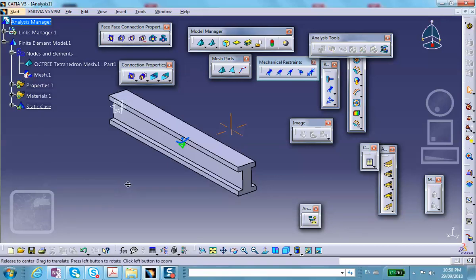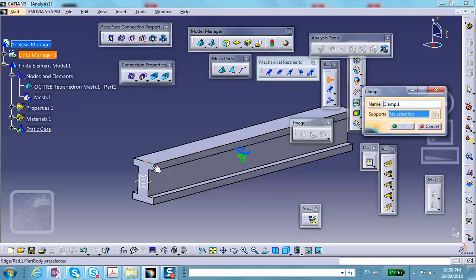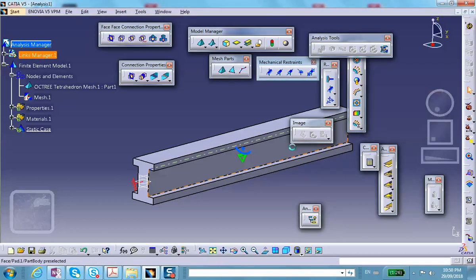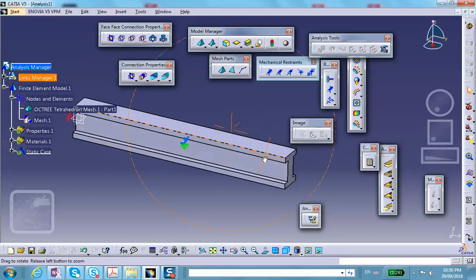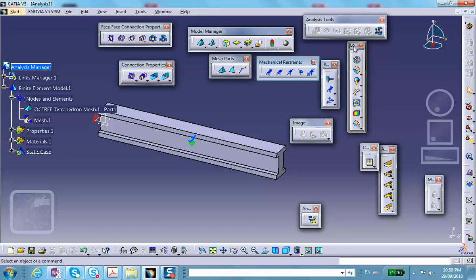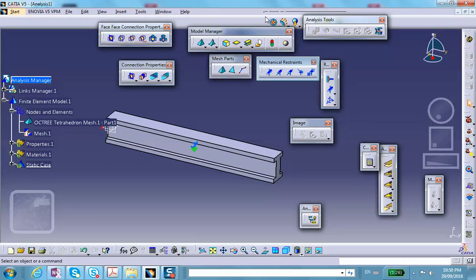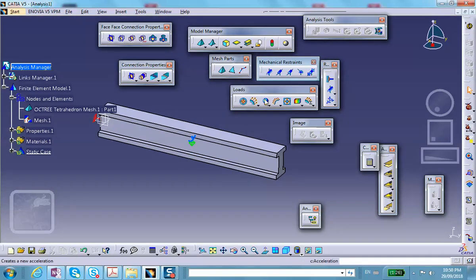All right, good. So this end is clamped. Where is the clamp? Right here. This face is clamped, and the load is coming from acceleration in the direction z, negative z. So where is that acceleration business? If you look at the loads toolbar, which is right here, where you use pressure and force and things like that, there is an icon here which shows a globe with a downward arrow. This is acceleration, linear acceleration.